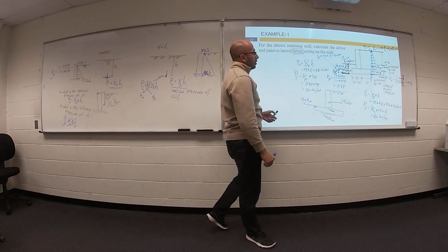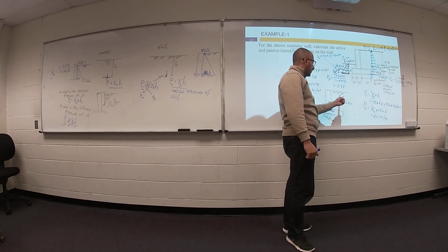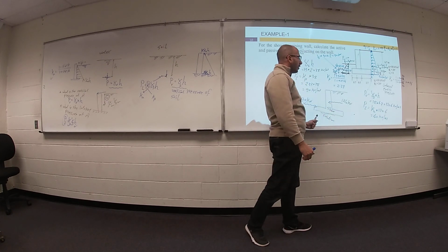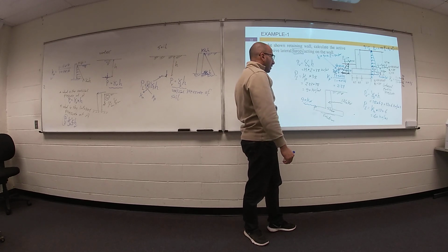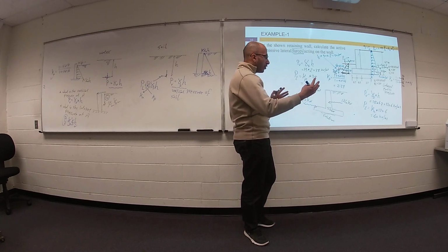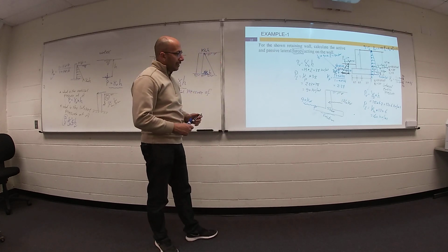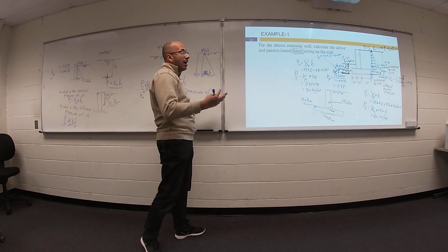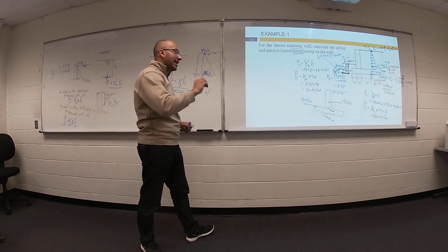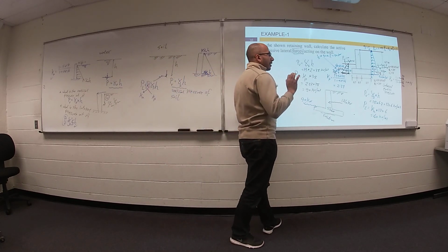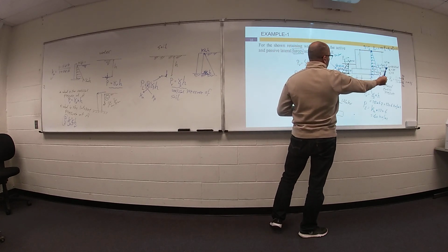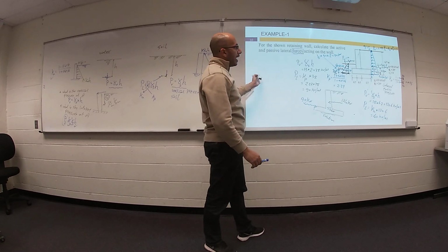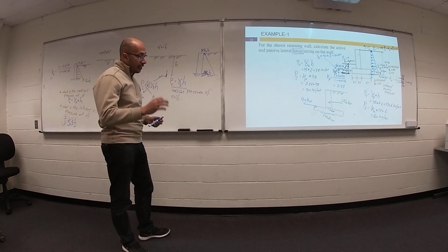However, although you have lateral pressure from this soil equal to 134, we have a reaction here from the other side, 90 kilonewton. So which one will cause sliding or overturning, or do you have stability? I'm not sure what will happen, but right now we can calculate how much force from this side, how much force from the other side, how much pressure from this side, and how much pressure from the other side.